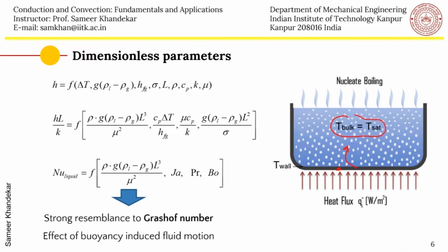It can also be subcooled, but right now we will consider that the bulk temperature is equal to the saturation temperature, let's say, if it is water at 1 atmosphere, then 100 degrees centigrade is the bulk temperature at P equal to 1 atmosphere. So this is a typical tea making at home. The water first starts at room temperature, but then fully developed nucleate boiling will start at 100 degrees centigrade bulk temperature. So there is a delta T.